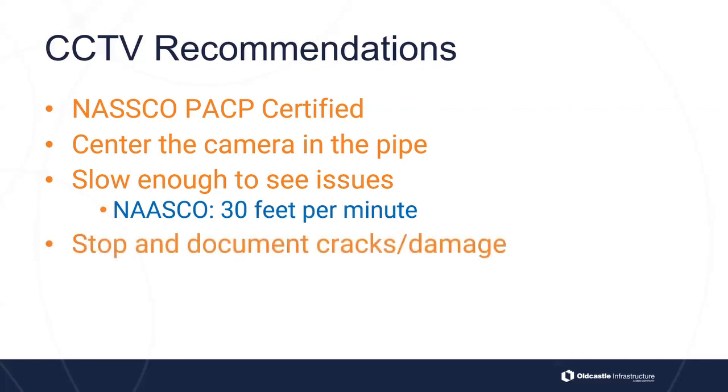I always recommend that they stop and document any cracks or damages. So if you're going through and you see a crack, they stop, they notify, they document it, they mark it on the screen, they code it correctly so that we can come back and review that. They put it in the report, everything.